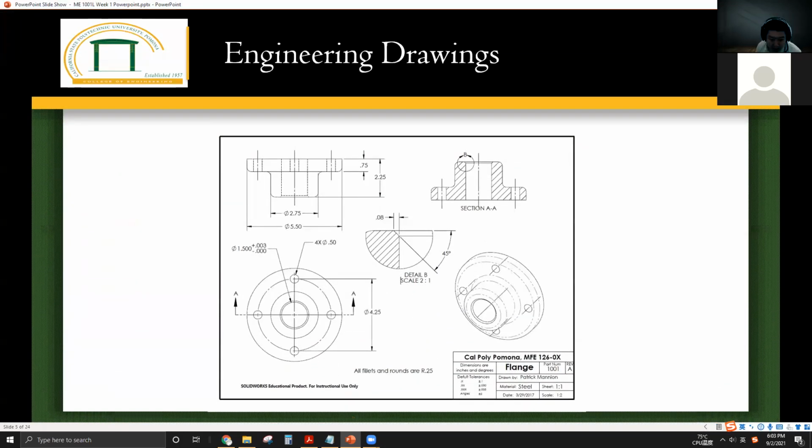So this drawing is of a flange, a very simple one. For those of you who aren't familiar with a flange, it means this piece is supposed to have another piece to form a couple, sometimes identical. You bolt these two pieces together with 4 bolts and nuts, or studs and nuts, whatever the fastener. And in the middle, you have a pipe going through the hub. So the flange is a very safe, leak-tight way to connect 2 pipes or 2 nipples.